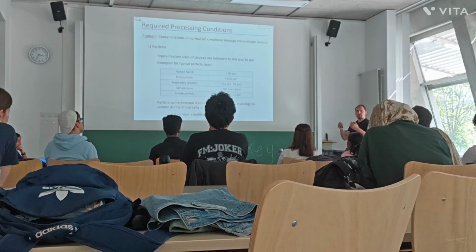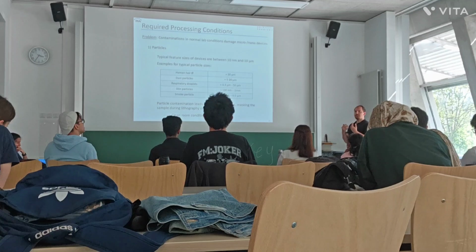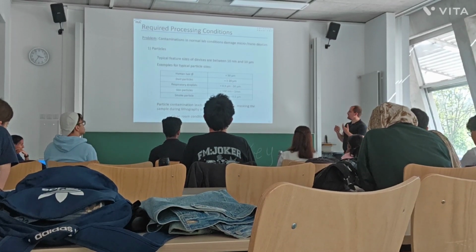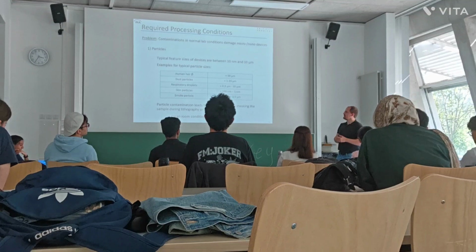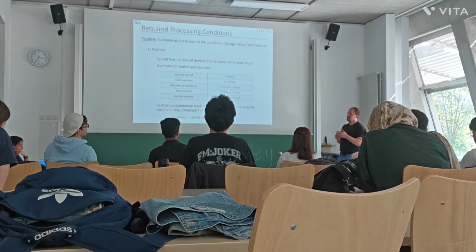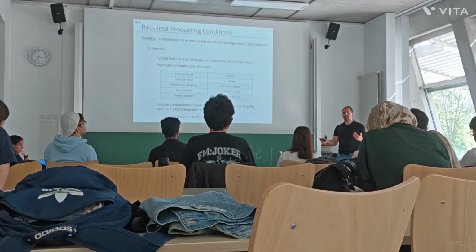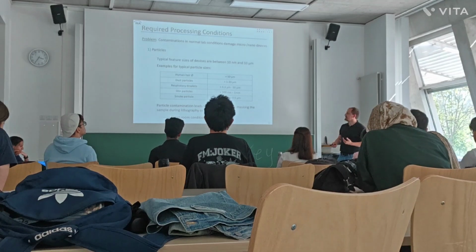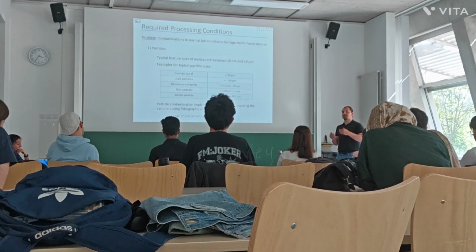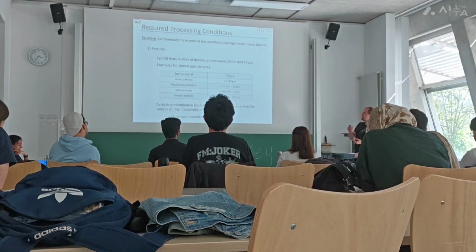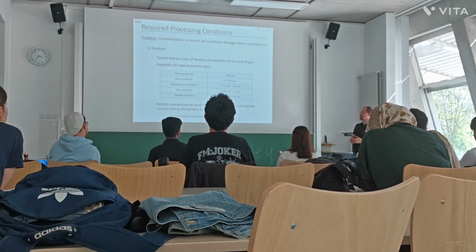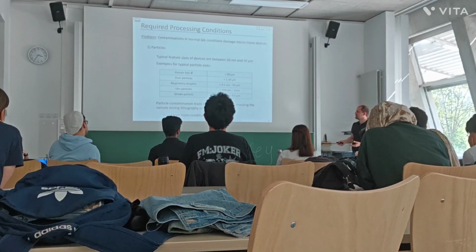So there's even a rule in our lab that if you are a strong smoker, in the industry you're probably not allowed to smoke. But here at the university we're a little bit softer. We say, okay, if you smoke, you have to wait half an hour until you can enter the clean room again, and you have to drink something before, so you don't exhale those particles, which would strongly influence the result of your lithography, etching, or deposition.